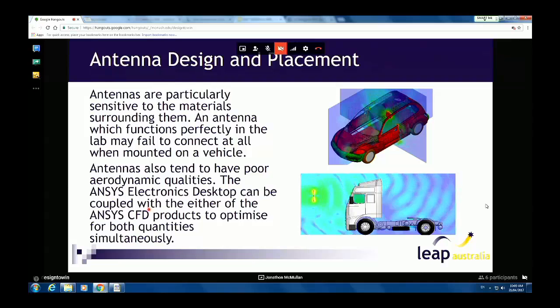So if you're able to change the covering dome of that antenna, then our Workbench interface can look at both designs, start tweaking, and make sure that we achieve minimum drag while still achieving the radiation efficiency that we require. So there are a lot of alternative designs that you can possibly do. As a side note, that technique was used to optimize stealth bombers. They want to look at the radar cross-section and they link it through to the shapes of the air intakes for the engines.